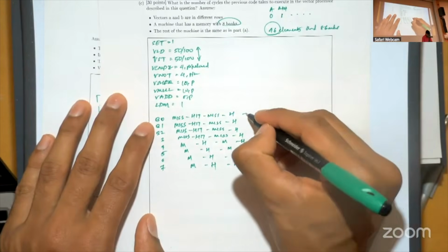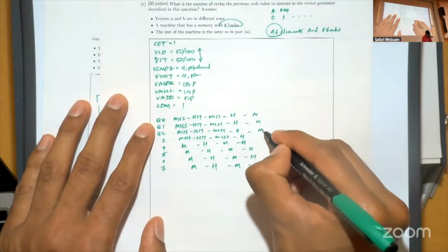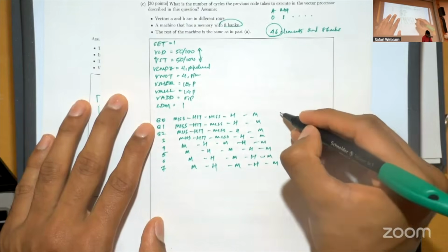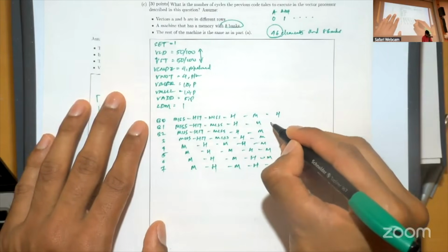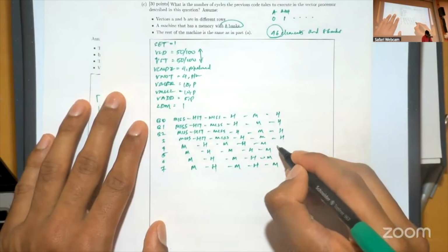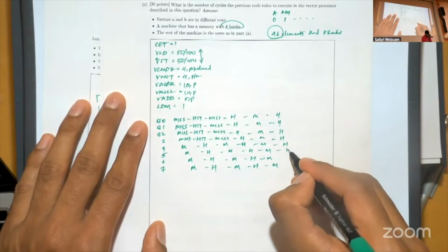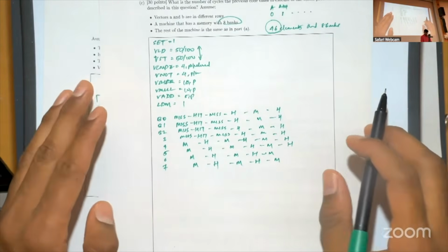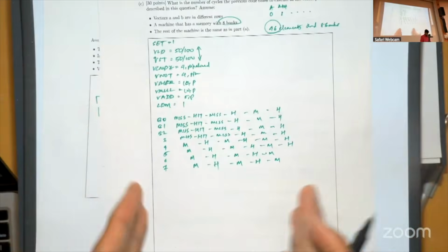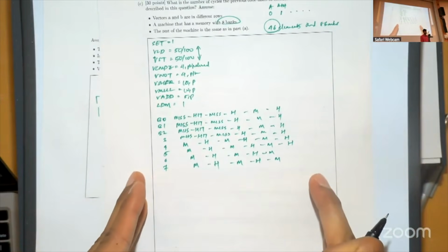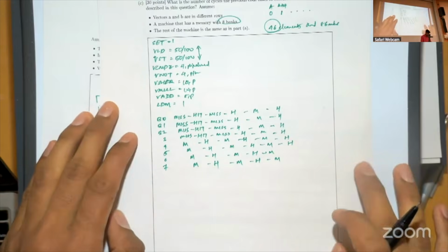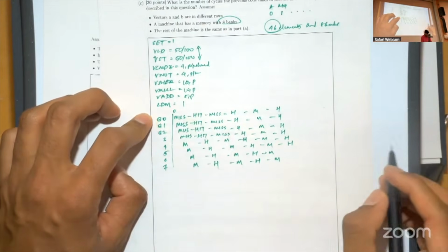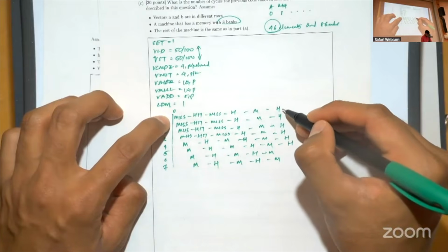Right? We're going to have another set of misses because this is 32. Here we would have 40 memory accesses done. And this would be 41, 42, 43, 44, 45, and 46. Your memory access latency for the VLD instruction will entirely depend on the longest running data fetch from the different banks. So B0, let's say, starts at time 0. It will take 6 memory accesses and it will be done here.